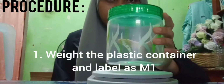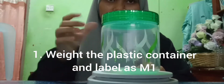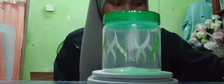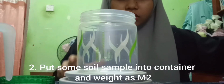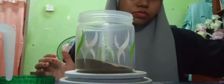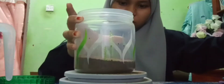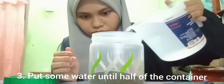First, weigh the plastic container and label it as M1. After that, put some soil sample into the plastic container and weigh it as M2. Next, put some water until half of the container.